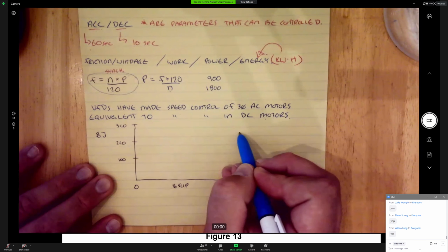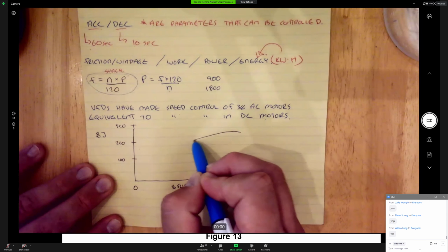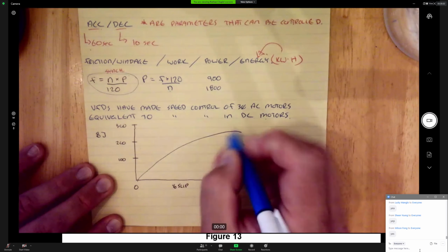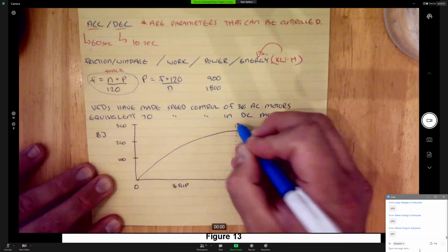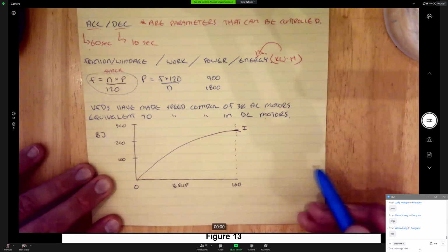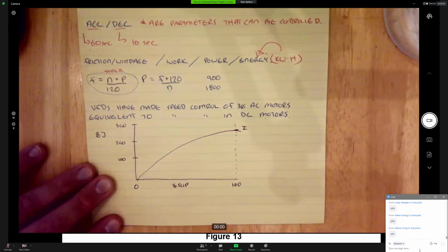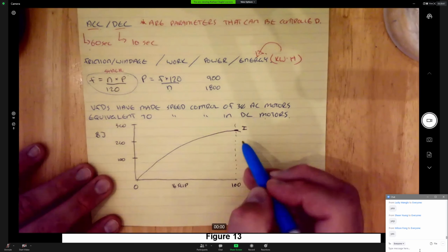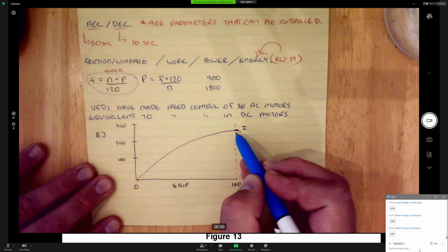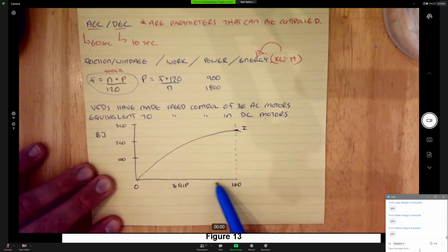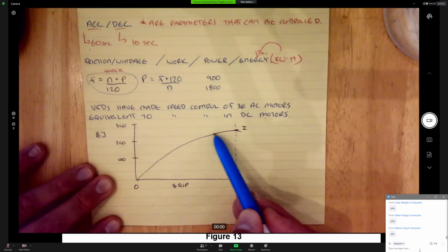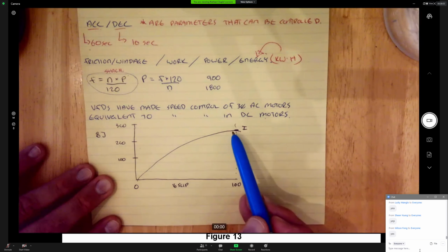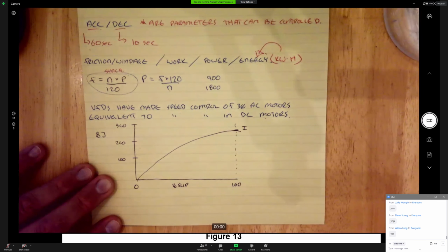And there's a few things on this diagram, and one of them is current. So this is the current, and if we draw a line straight up, we all know when we start a motor, the instant the stator is energized, we draw a value of current called inrush current. And as the rotor accelerates from 100% slip close to a 0% slip, this current is going to decrease. So this inrush current will not persist for too long.